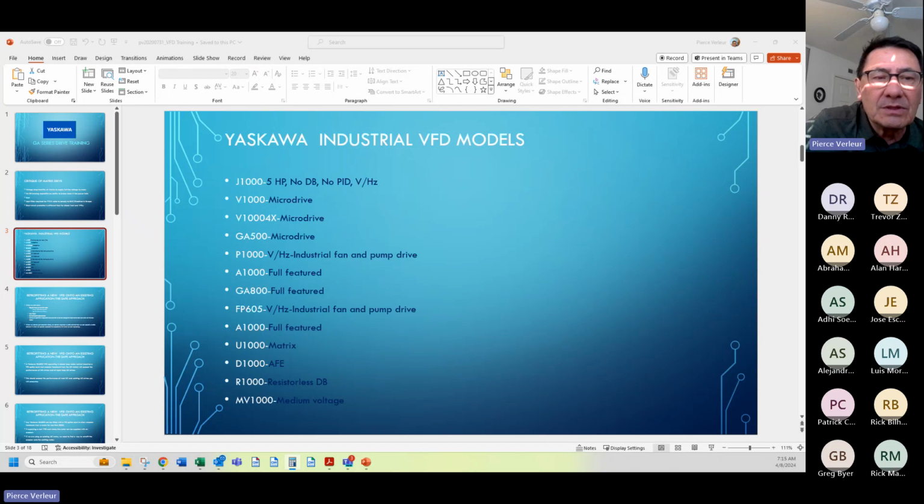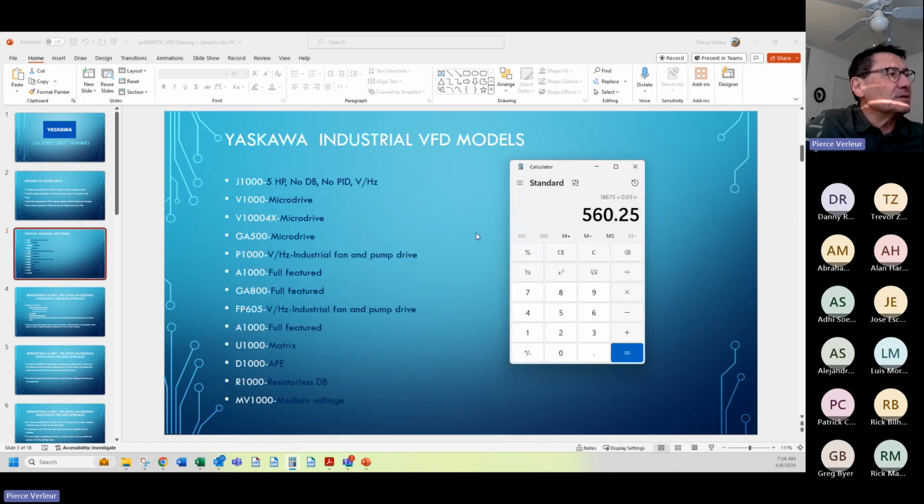And thus we were able to waste off 80% of that energy. So here's the 560 total watts loss on a 25 horsepower drive times 0.8 using the flat heatsink design. We're getting 448 watts of that out the back. And therefore, you only have about 120 watts, or one light bulb, inside the enclosure that you have to dissipate.